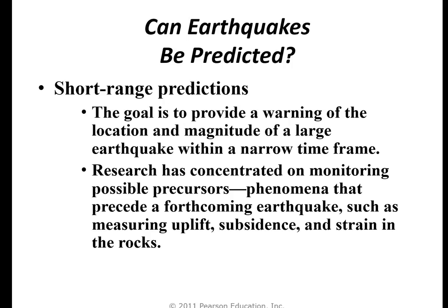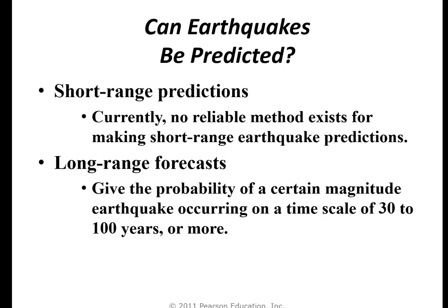Well, can earthquakes be predicted? Short-range predictions. The goal is to provide a warning of the location and magnitude of a large earthquake within a narrow time frame. And research has concentrated on monitoring possible precursors, phenomena that precede a forthcoming earthquake, such as measuring uplift, subsidence, and strain in the rocks. Currently, no reliable method exists for making short-range earthquake predictions. Long-range forecasts, though, give the probability of a certain magnitude earthquake occurring on a timescale of 30 to 100 years or more.